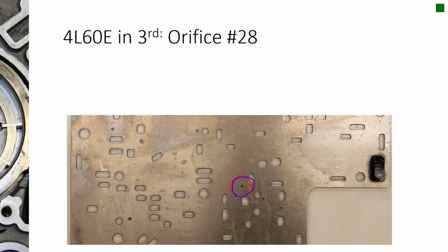For example, when you go through an air test, if you remember when you air test that 3/4 clutch, there's an air bleed in there. You have to put your finger over it because you'll always hear it leak if you don't put your finger over it. So there's an automatic engineered leak that is in that 3/4 clutch circuit. Also, in the servo assembly, there's an air bleed in it.